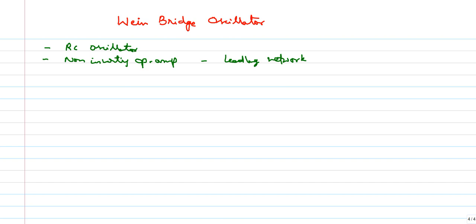With the RC phase shift oscillator, we have already completed the combination of R and C, which is suitable for transistor type of circuits. That means we can use any of the transistor topologies, maybe common emitter. We can use it in voltage divider format, and we can take the feedback from the output of the transistor and give the same thing to the feedback network. What is the feedback network? The RC circuit is the feedback network in the RC phase shift oscillator. That part again we need to give back to the transistor. This is what exactly happens in the RC phase shift oscillator.